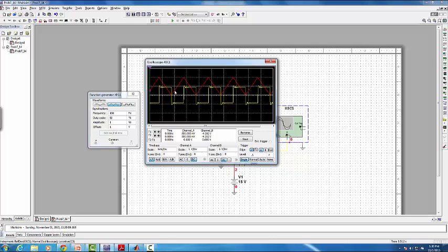Channel 1 is in 1 volt per division, so that's up 2 volts. Channel B is in 5 volts per division. So, ooh, I'm off by a factor of 2. So I'm going up 4 and down 4. But the point really is that the ramp function, the derivative of a ramp, is a step function, and we indeed see that in the circuit.